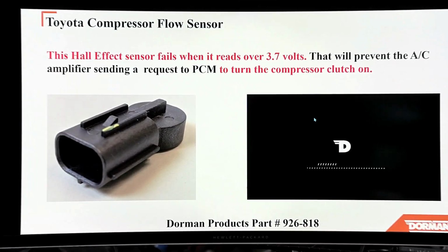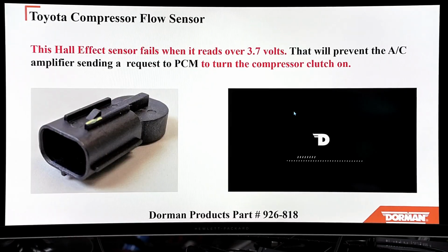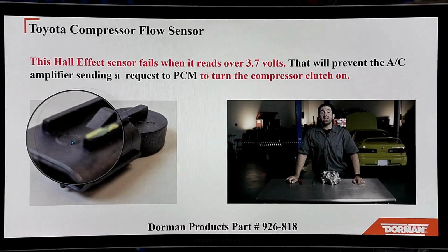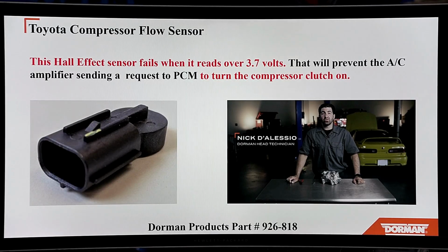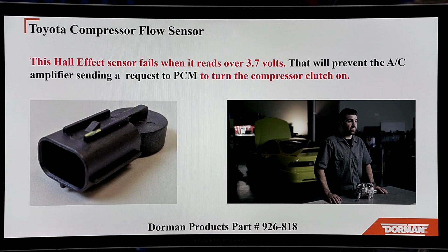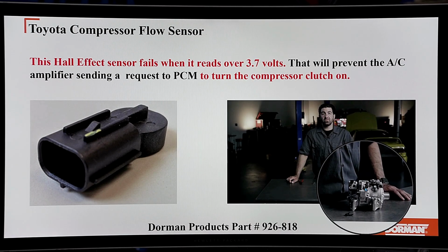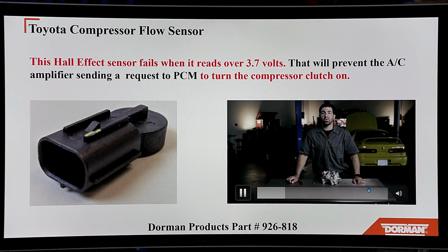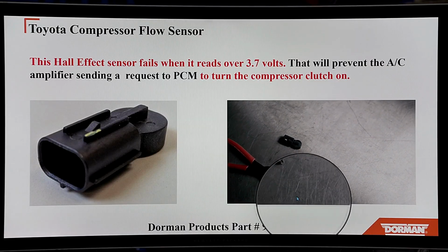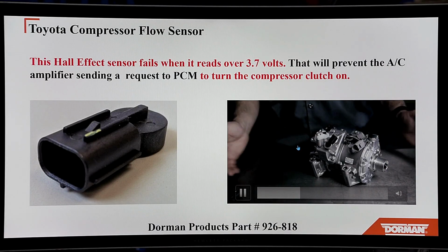Now, this is a great part. I'm going to show you this on the video. I'm not going to play the sound. I'm going to talk through it. Yeah, Dorman, but guess what? This is a part we use here in the shop, and as he's going through on this compressor, this piece is located right here. Toyota or other companies want to sell you a whole compressor. Well, you don't need that. You take that snap ring out. Here's the component we're going to put in, and you put this piece in right up top.